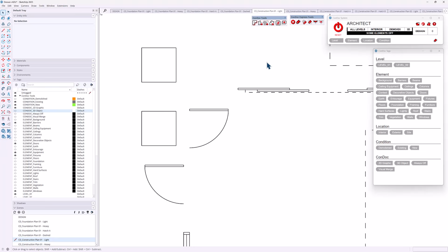All right, so if this wasn't working, and I'm trying to think on the spot why it worked, which is good news, it worked, but there's this button, scene, update, and save. So after tagging changes, this operation updates the scenes with the correct visibility of entities and saves the file. So if for some reason we tag this and then it was like, man, why is this still not showing up?